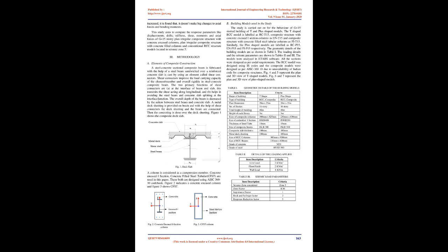Sachin [2] presented a paper on the seismic behavior of a 15-storey irregular building through dynamic analysis as per IS 1893:2002 for seismic zone 4 and medium soil type. The results were compared for various parameters like time periods, frequency, storey drifts and storey displacement. CFST columns were compared with the CEC columns.